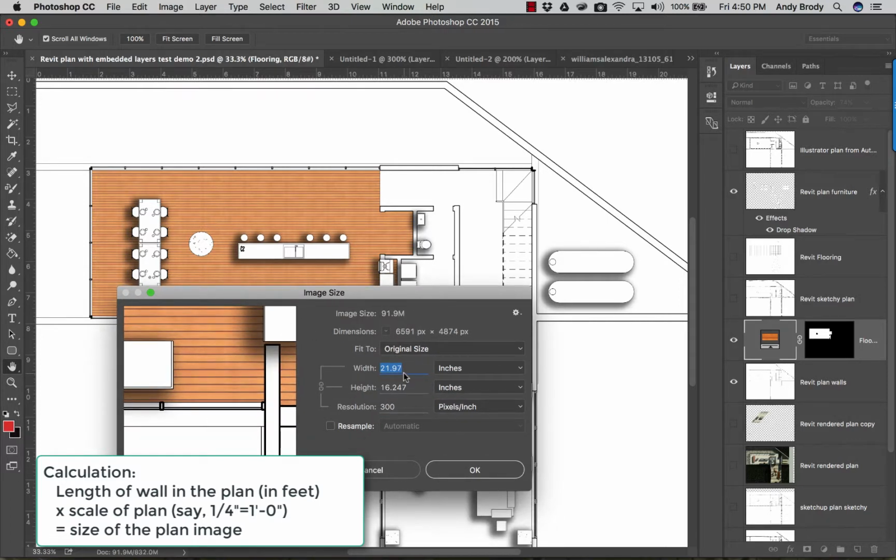What I would want to do is make sure that I change the size of this image, and usually I leave this resample button off because it will mess around with things. I don't want to lose any pixels. But if I know the image should be, say, 10 inches wide, just come and change it, and it will resize the image to be the correct size at whatever resolution it ends up being.